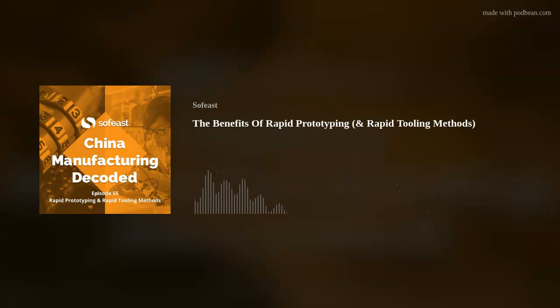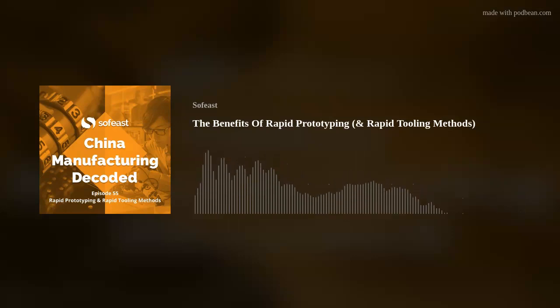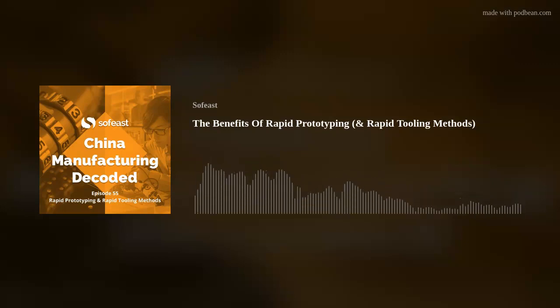And the problem with a porous surface is that you cannot do certain types of finishing. So a lot of products come to us with some really nice looking designs, and then they say, well, it needs to be anodized, because when it's anodized, wow, we can make it in that color, and it's beautiful. That's right, but then are you going to fight the fight of anodizing over a cast part?